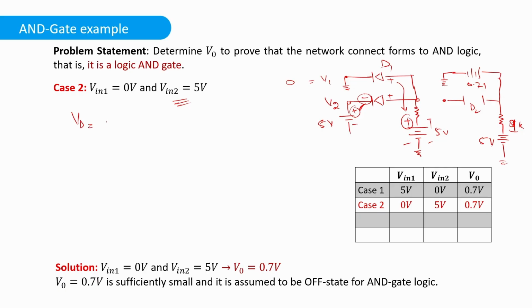We know this, that the voltage is always 0.7 volts if it is made using silicon material, right? So now the output at this point, which is V naught, will become the output measured using this terminal and this terminal, right? So if we look at this figure, it will be between this terminal and this grounded terminal, which is 0.7 volts.